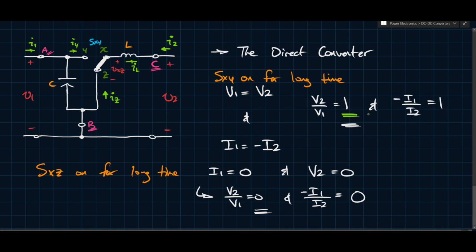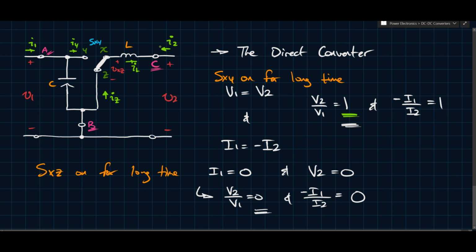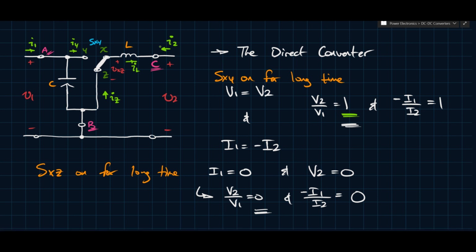And we see that the power balance, meaning the input power and the output power, which is a consequence of the conservation of energy, dictates that the current ratio should be negative and the inverse of the voltage ratio. What that means is I've drawn I2 going inwards, but in reality we expect that I2 will actually go the other way. The reason we're drawing them going inwards is we're assuming that the direction of power flow right now is general. We haven't assumed any type of external network, we haven't assumed anything about anything else. We're just assuming that we have this network. These are the definitions we've done. Kind of like when we saw the transformer, we always define currents going in towards the transformer, and if it's going the opposite direction, we just give it a negative sign.